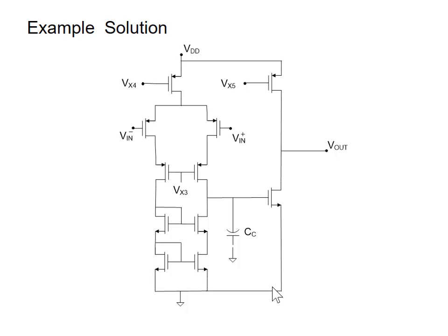Okay? Yes? When we're doing this method for compensation capacitors, are we tying it to VSS all the time? You can tie it to any DC node in the circuit you choose. Compensation is dependent upon small signal analysis, assuming it's linear. You can show that VDD and VSS, and if there's a separate ground, they're all the same potential in the small signal circuit. So it makes no difference which place you connect it. Good question. Does that make sense?